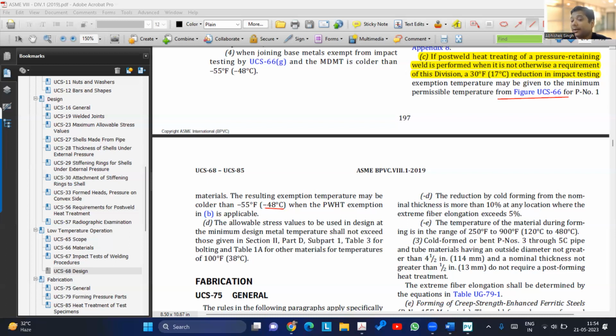And because of that, what happens? Do we have any change in design if we follow RT1 or RT2? The thickness, if we talk about it? Yes, joint efficiency will vary. Thickness may vary when your longitudinal forces are governing. Otherwise, it will not.